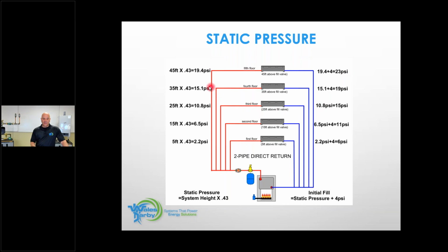And we break it down, whatever your height of the building is, it will tell you what your operating pressure should be. So here, we're all the way up to 25 feet and still with the typical setting on a feed valve, we're within 3 PSI. Here we're 15 feet, we're at 11 PSI. So right around that 20-foot mark is where you're going to start to say to yourself, do I need to change the system static pressure? And again, no matter what I do here and here, it has no effect on this. No effect on the circulator sizing.